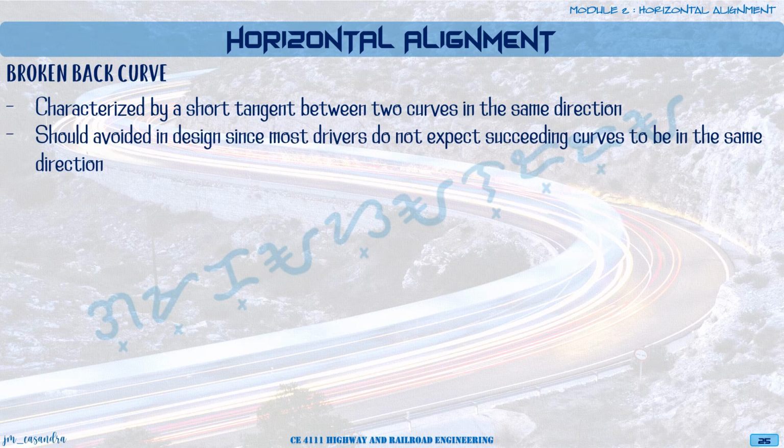Okay? So usually broken back curves would be avoided as much as possible in our design since most drivers would not expect succeeding curves to be in the same direction. Okay? So okay lang kung curve and then another curve yung same direction ng movement natin. Pero usually sa drivers, they would not expect having a curve and then a straight line and then another curve in your road section or in your highways. So usually this is avoided in highway designs. So this is what a broken back curve would look like.